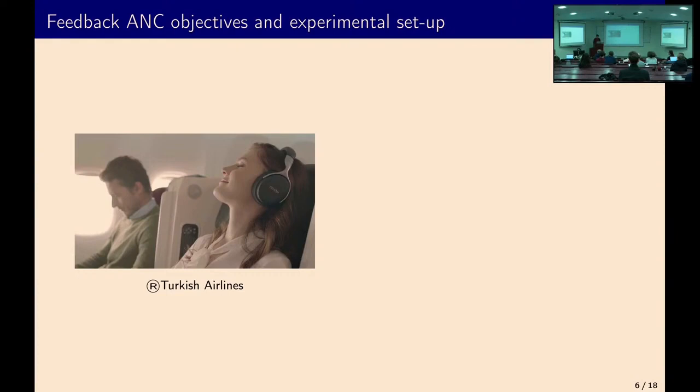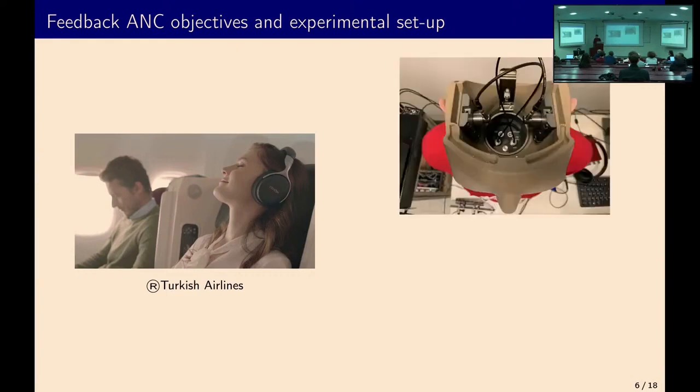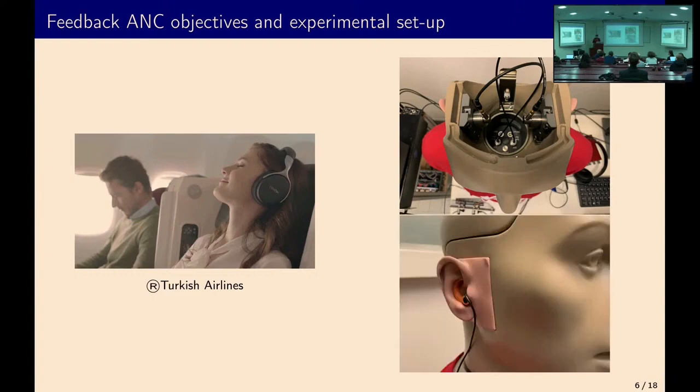Since we cannot use the students as guinea pigs, we use the dummy head, the one you saw just on the picture before. It has two microphones simulating the eardrums of the listener. And the control microphone, which in the case of a company headphone is located at the optimal position, in our case is an external microphone placed inside the ear, just to be able to change the headphone and replace the passive headphone. Okay.